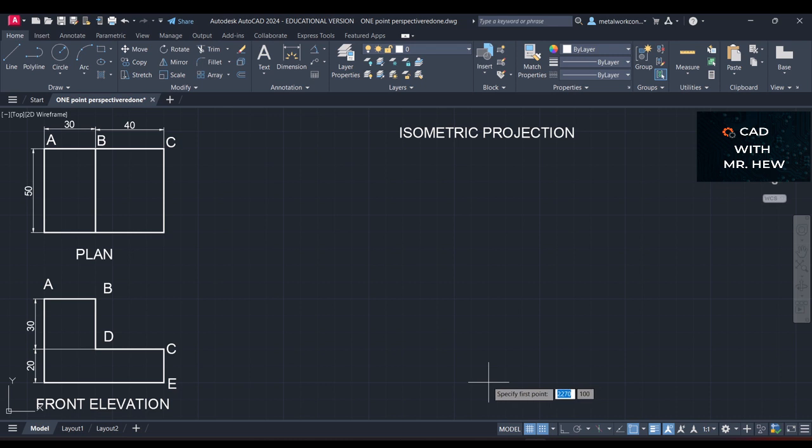All right. Now the first thing that you'll draw, if you are using the traditional T-square, is a horizontal line to represent the T-square line, right? I'm gonna put it right here. This line would be about 30 millimeters long. You don't really have to measure it. And then you draw a vertical line going up. It could be any measurement because it's a construction line. So these two lines would have been drawn with the T-square and a set square to form the starting point for the isometric projection, right?